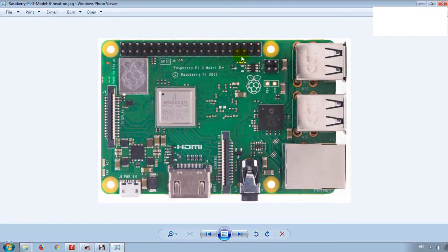From all these 40 pins, on this specific board, we have access to 26 of them as input and output. Also, some of these pins can have other hardware functions that need to be configured through our code. For example, one pin can be configured as PWM, pulse width modulation, which can control a DC motor by making a square wave with different duty cycles and different wavelengths.